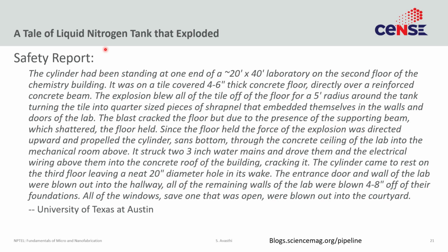But someday, the liquid nitrogen tank was not used for a long time. Internally the liquid nitrogen evaporated, the pressure built up in the tank, and one night it exploded. When it exploded, it was stored on the second floor of the chemistry building. It was on a tile covered with 4 to 6 inches thick concrete floor directly over a reinforced concrete beam. The explosion blew all the tiles off the floor for a 5 feet radius around the tank, turning the tile into quarter-sized pieces of shrapnel that embedded themselves into the walls and doors of the lab. Imagine what if somebody was there inside. The blast cracked the floor, but due to the presence of the supporting beam, the concrete beam underneath, which shattered, the floor held.